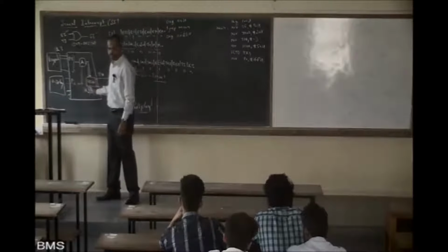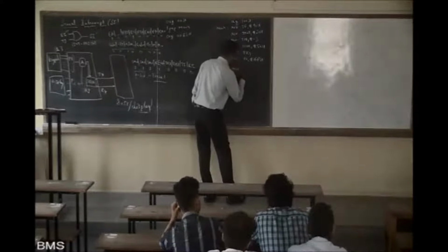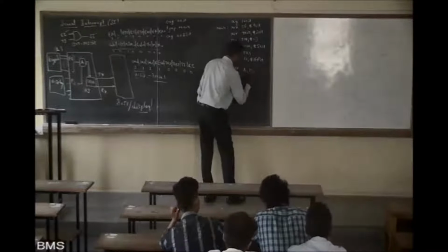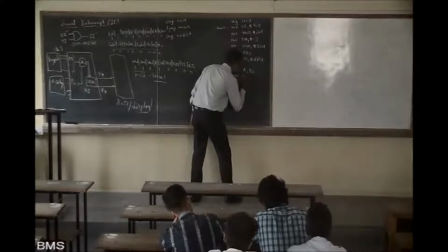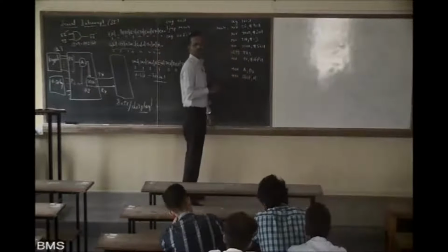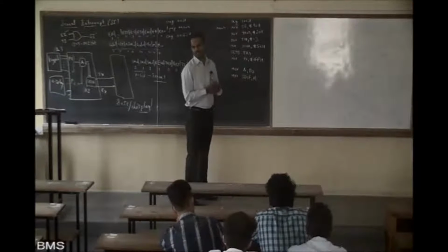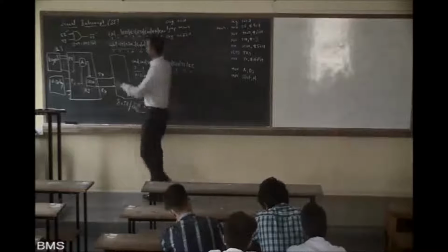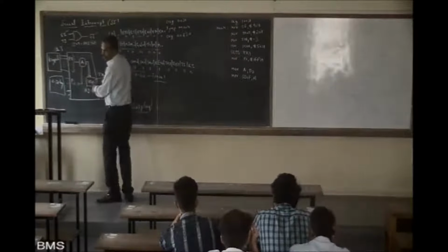Move the value from A to SBUF. From where is the value that you get? So what I do is move A comma P0, move SBUF comma A. From P0 I have taken a value to A, from A I have put it to SBUF. Next, what should I do?